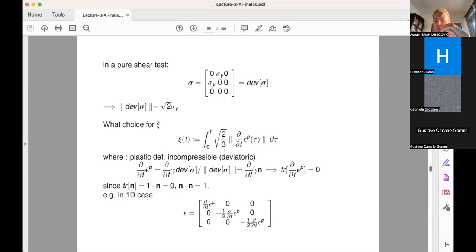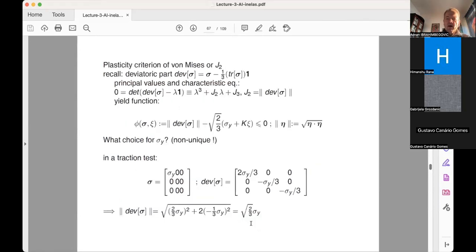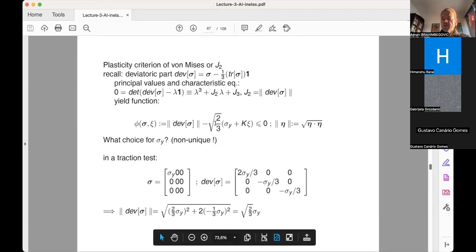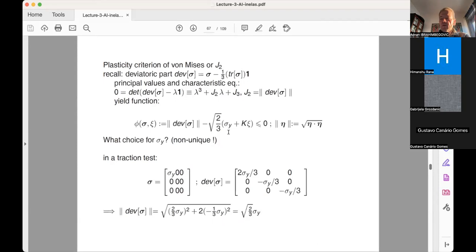So if the plastic deformation is much bigger than the elastic deformation, which is the case in many practical applications, I have behavior which is called quasi-incompressible. And we'll see that that requires a special handling of the finite element interpolation, otherwise you get in trouble. Again, the method of incompatible modes that we talked about is very useful, but you have other types of interpolations as well. So this is the reason why I had to have this square root of 2/3 for two different reasons, but they happen to be the same factor, so it really simplifies the writing.